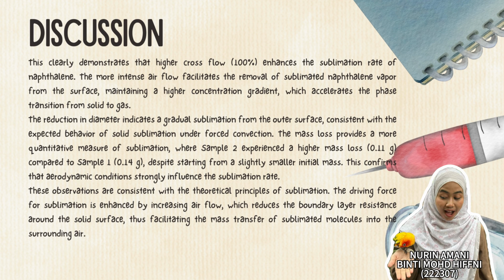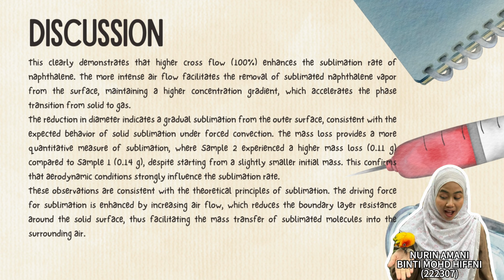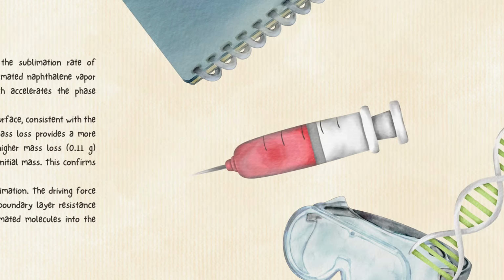These observations are consistent with the theoretical principle of sublimation. The driving force for sublimation is enhanced by increasing airflow, which reduces the boundary layer resistance around the solid surface, thus facilitating the mass transfer of sublimated molecules into the surrounding air.